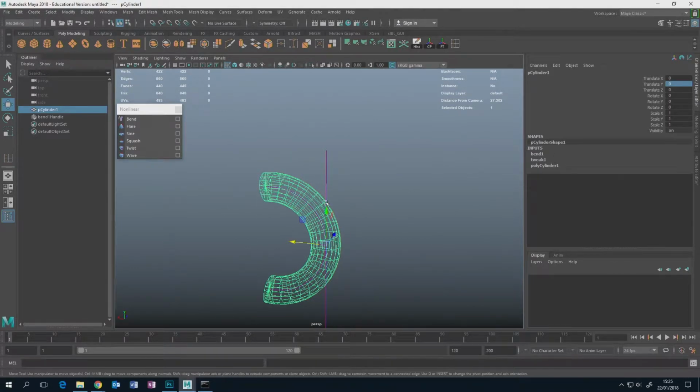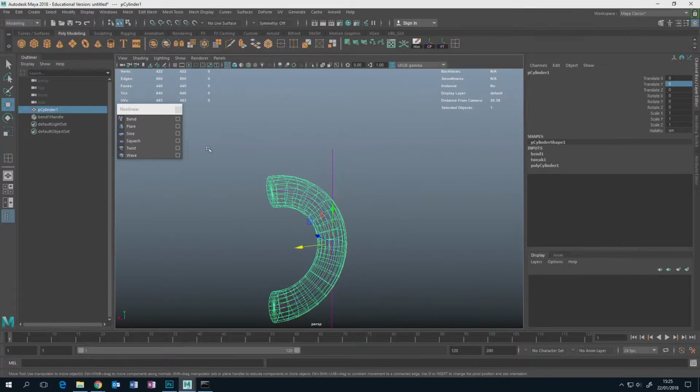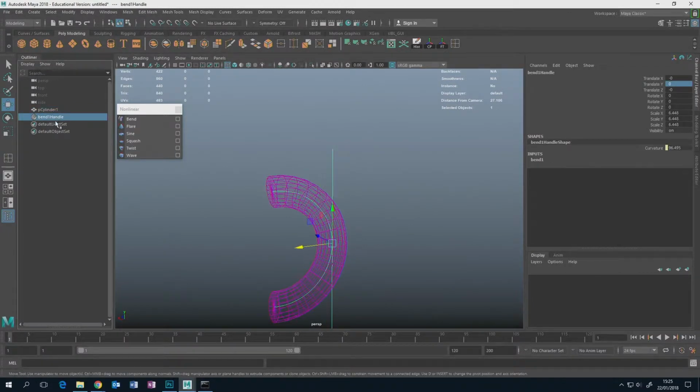Now that I've got that set up in Edge Tools, if I make a button out of that, it's always going to split it by 3, like that. So remember, when you create a button on the shelf, it's going to remember the settings that you last put into here, or it's going to remember the default settings if you've never messed around with these settings. So yeah, creating buttons on the shelf.